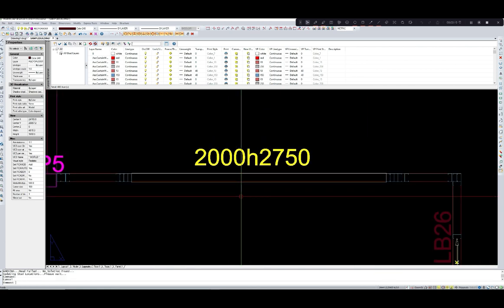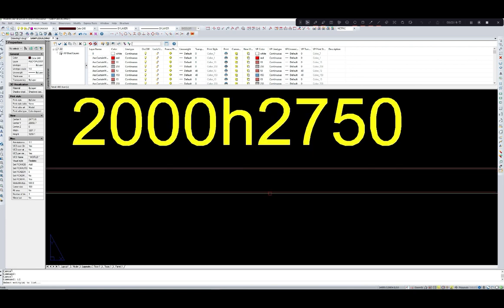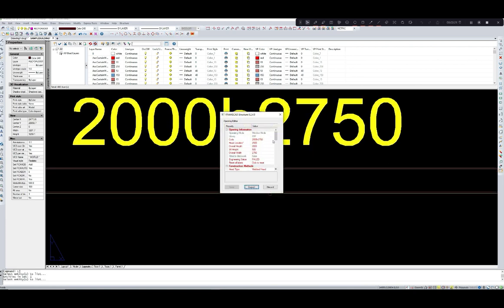Now let us check listing of this opening. Now you can see everything is in red. So that means this opening is failing. We might have to strengthen it, whatever available option in FrameCAD has been already utilized. So we have to go for providing a MS beam or MS column for this lintel.